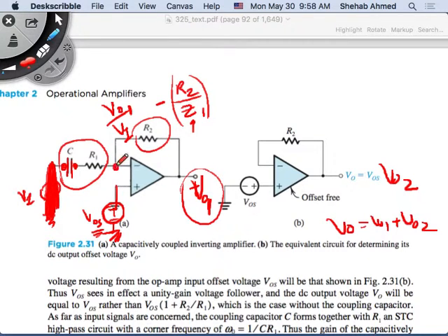What is the voltage here? Because we have feedback? No. Offset. Right? This offset voltage is a DC value. This DC value can push current through here if there was no capacitor. But because I added the capacitor, it is an open circuit for DC. So that's why the circuit became this. Okay, so because of the offset, C is a short circuit? No, C is an open circuit. Exactly. So C is an open circuit.